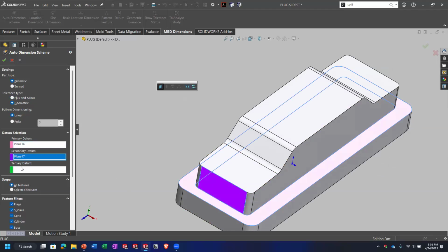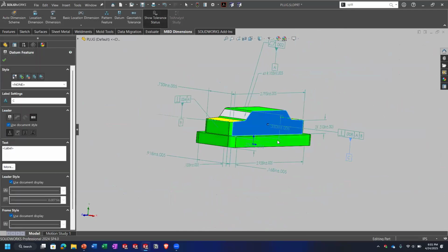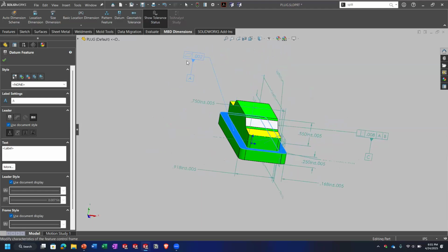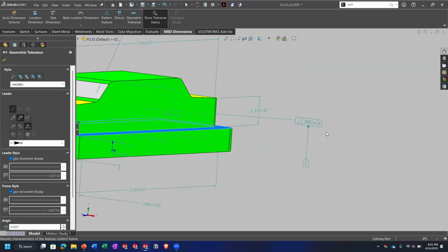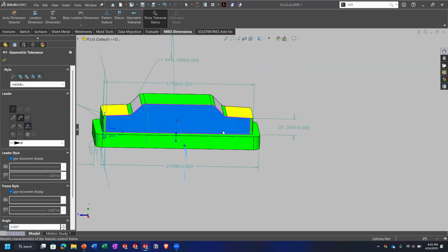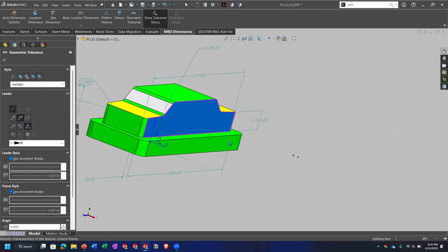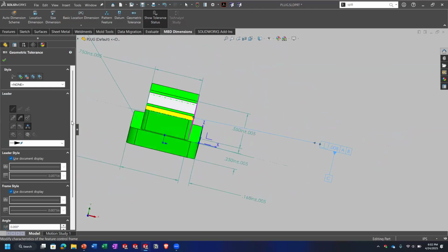So I can call out using geometric tolerance type versus plus and minus. And when I do that, I'm just going to quickly click these. I should get a datum established here. Yep. So we've got datum C, datum B, and datum A now. And again, based on the template settings and its interpretation, it made a guess on what I would want. And in reality, do I care about that being perpendicular in relation to datum A? No, probably not, but not a bad guess, and I could make those changes pretty easily. So I could just delete that tolerance.